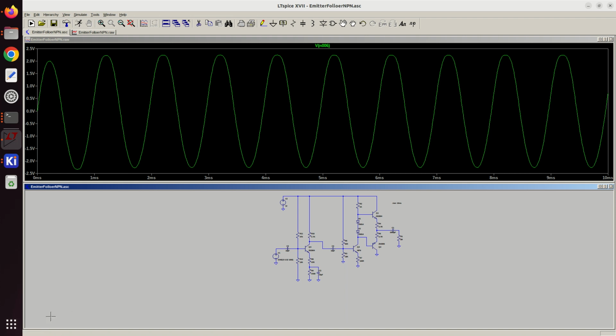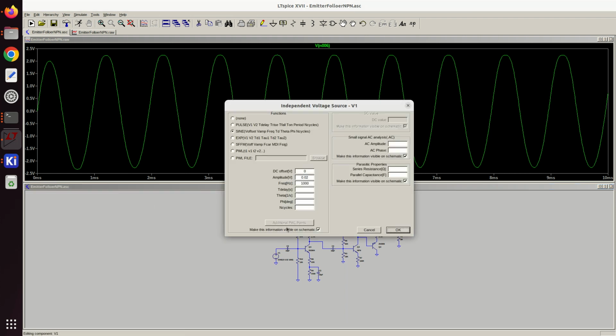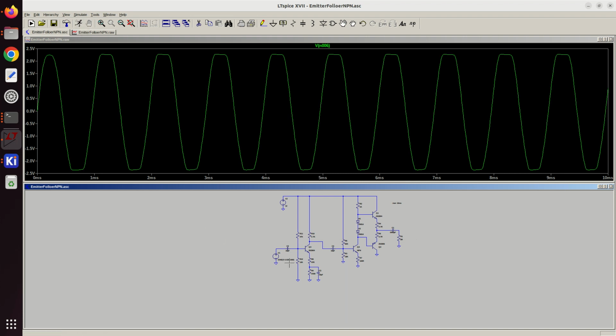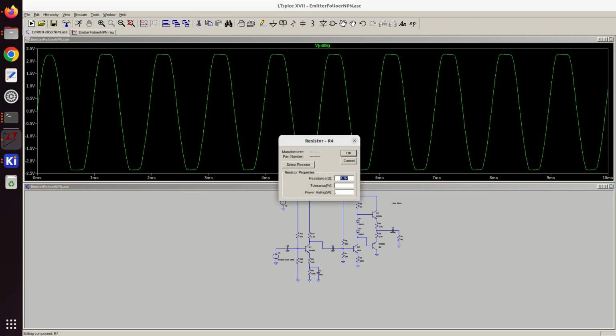I'm looking down in this area. So we're at minus 2.288, and at the top we are 2.26. So I think it's starting to clip there, but let's see. So 0.25. And it's clipped in both of them now. Might be worth, just for simulation purposes, making this really small, because these do have an effect on it.